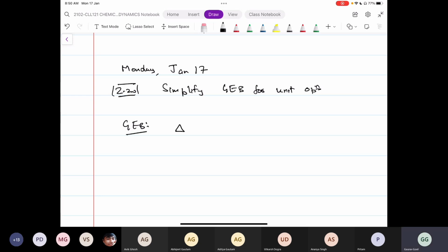So let us start at the general equation. I am working in terms of mass flow rates, but if there is no reaction in the system, you can as well write everything in terms of moles. Of course, all the quantities you will need to change. For example, 1/2 u squared, z g, these are specifically the kinetic and potential energies in terms of per unit mass.